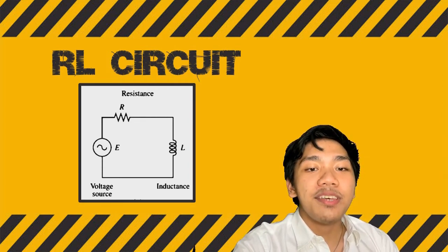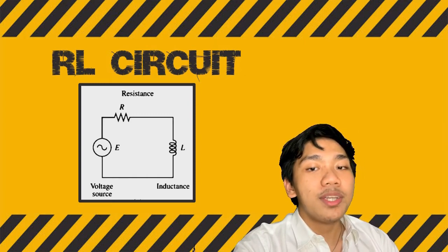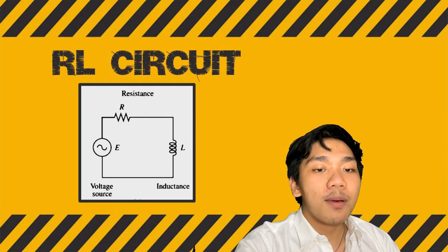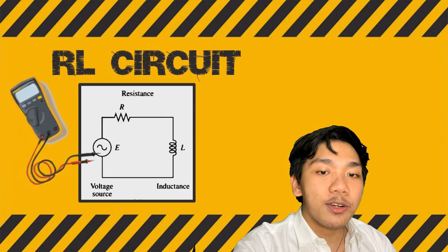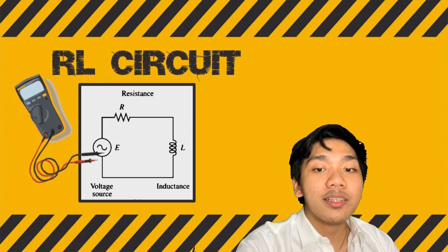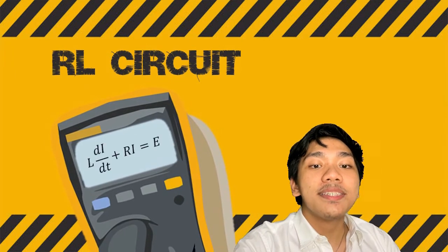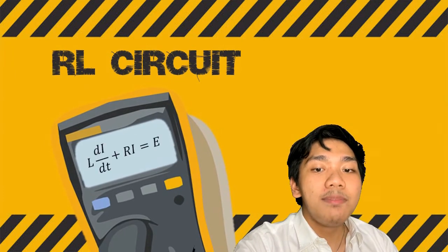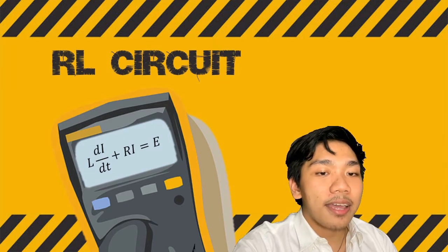The formula used to evaluate the RL circuit is given by Kirchhoff's voltage law, which states that the algebraic sum of all the potentials around a closed electrical circuit is zero. Applying this law for an RL circuit, we have the voltage E is the inductance L, Henry in units, times the derivative of the current, amperes in units, with respect to time, plus the product of the resistance R, ohms in units, and the current I.